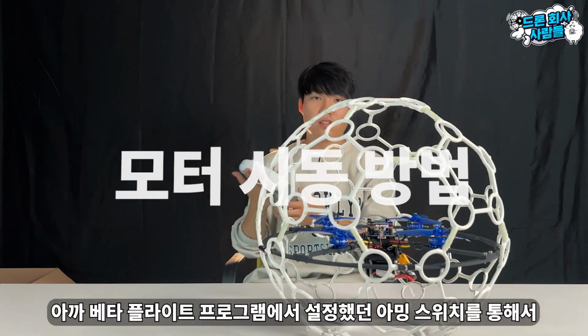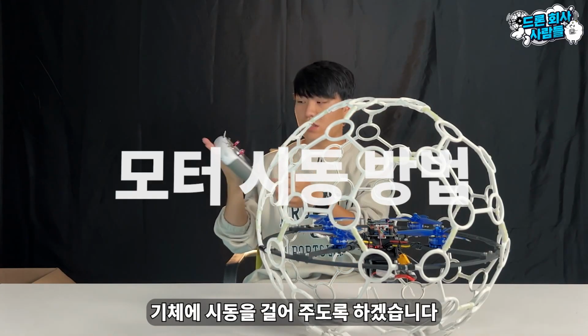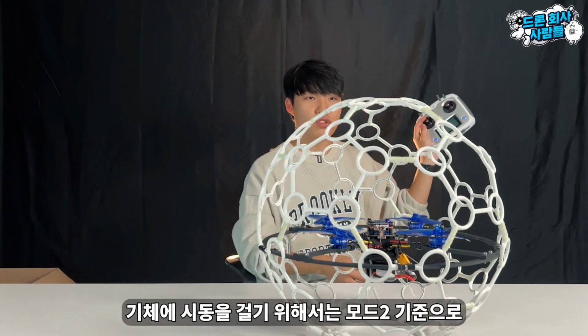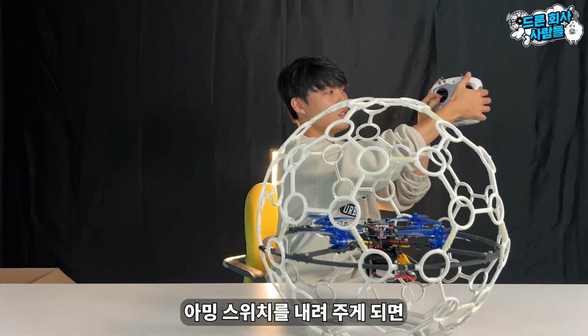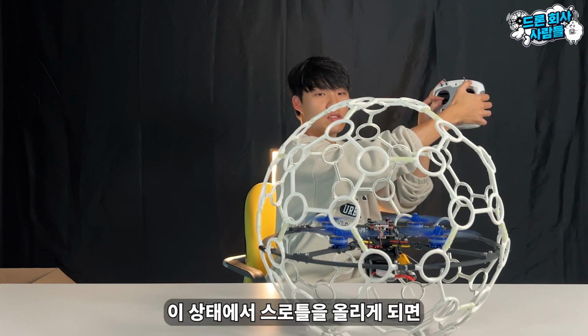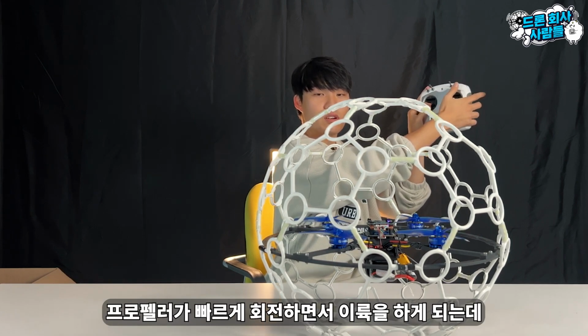We will start the aircraft using the arming switch we set in the Betaflight setup program. To start the aircraft, with the throttle on the far left in mode 2 lowered, activate the arming switch and the propeller will start spinning, initiating the engine. In this state, when you raise the throttle, the propeller will spin rapidly and it will take off.